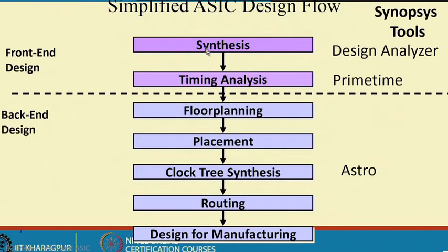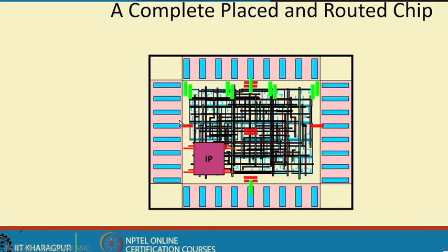This front end part, the specification, then the architectural definition, then synthesis, then simulation, then timing analysis, all this part is common in both design styles, but this portion, the device programming, in ASIC design has to be done manually, whereas you get it ready made in the FPGA design style.